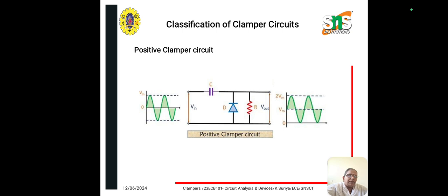Initially, the positive half of the applied input voltage signal reverse biases the diode, but the capacitor is not still charged. So at this period of time, output will not be considered. For the negative half cycle of the AC signal, the capacitor now gets fully charged up to the peak in the AC signal, but with inverse polarity. So this negative half forward biases the diode, that results in the flow of the forward current through the diode. The next positive half then reverse biases the diode, due to which the signal will appear at the output.